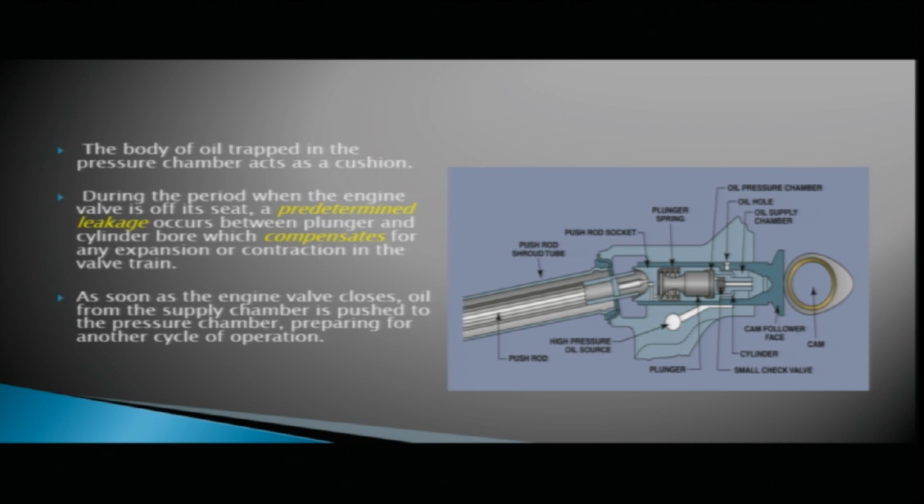As soon as the engine valve closes, oil from the supply chamber is again pushed to the pressure chamber, which prepares it for another cycle of operation.